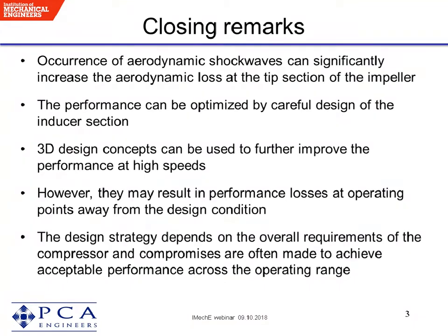I think mainly the reason is that at the outlet of the impeller, the channels are narrow and there's a very strong mixing taking place, and so a freeform design is not necessarily any improvement. Those of you who know what a pipe diffuser is will understand that that is quite a complex type of diffuser, where this mixing tends to be enhanced by having a very complex leading edge of the diffuser.